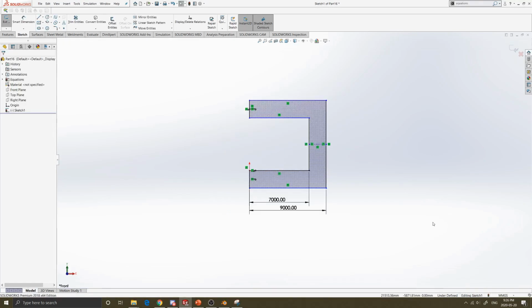So SolidWorks has a very interesting tool that you could use when it comes to smart dimensioning things. As you may have noticed, when you enter numbers, those are just numbers. But in computer science, or just computers, you can replace those numbers with variables quite easily. The same thing can be done in SolidWorks.